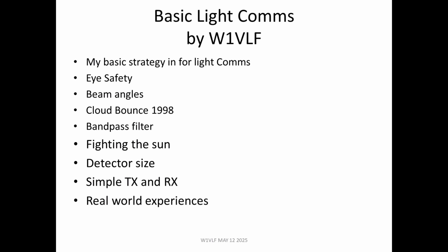And bandpass filtering. Bandpass filtering applies here just like it does in the RF world, only it's an optical bandpass filter. We're using 940 nanometers. Why 940 nanometers? Because back in the 90s, I worked for a cable company, and I could get all the old remotes for free, and you'll see more about that later. And they were on 940 nanometers, so I kind of stuck with that over the years, as I developed new receivers and transmitters and whatnot.